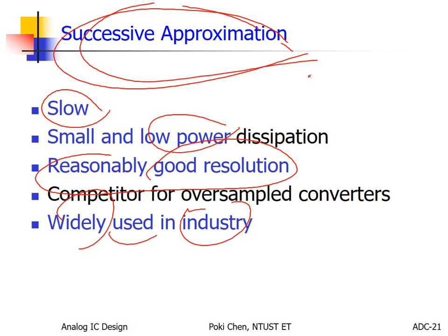But pipeline is much harder to design because you need digital correction, which is really troublesome. So my recommendation for your first ADC is to go with SAR, or if you need a very high frequency one, then flash. But for your future, if you would like to focus on ADC, you need to be familiar with SAR and pipeline at least.